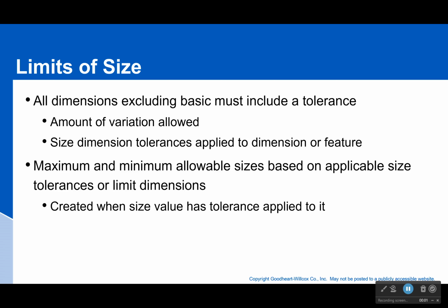Okay, now let's talk about limits of size. So all dimensions on your part, excluding some basic dimensions, must include a tolerance. Okay? Must include a tolerance. That will be a reference dimension we have in parentheses. Now, this tolerance is the amount of variation that's allowed.